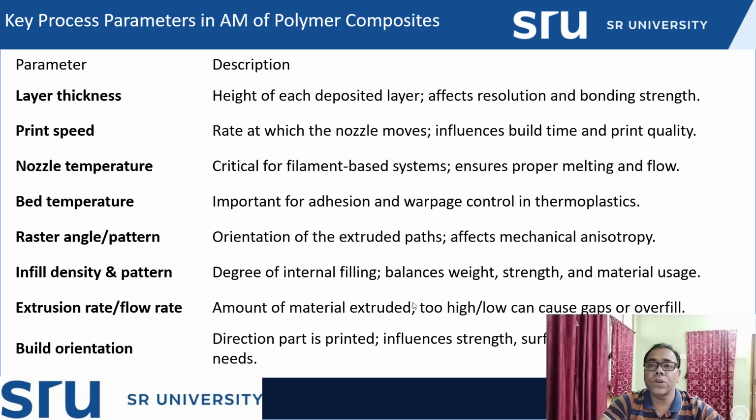But sometimes we do not require that inside material, so in that case one can go for decreasing the infill density, like 80%, 70%, 60%, 50%, even 20-30% also, no issue. In that case you are going to save material if that much strength and other properties are not required.